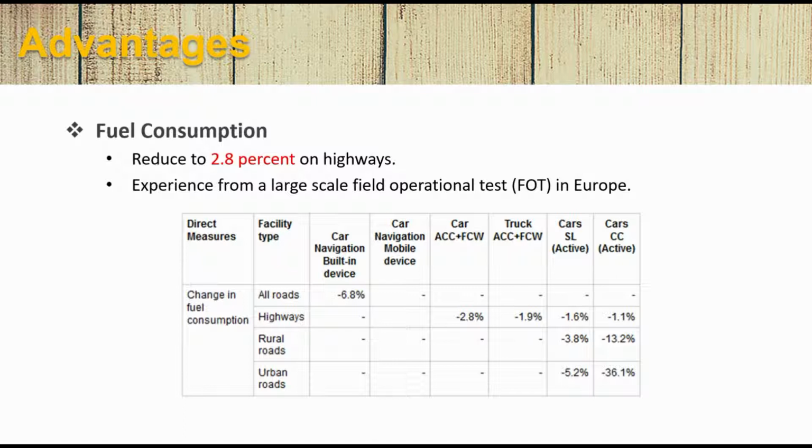It automatically adjusts speed in order to maintain the proper distance from the vehicle ahead of it in the same lane. The radar not only senses traffic ahead but also collects yaw and steering data to determine the targets in the chosen path.